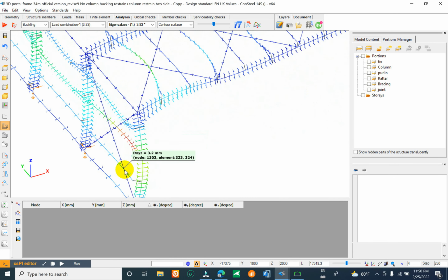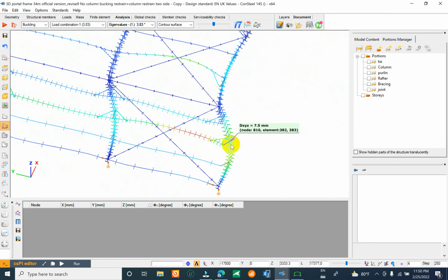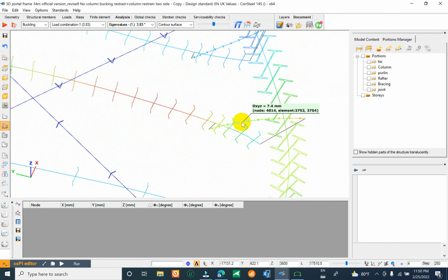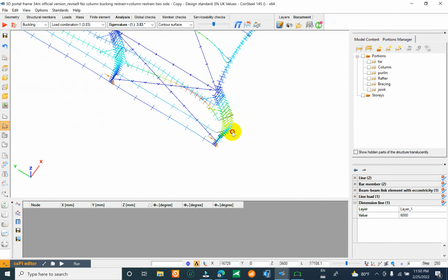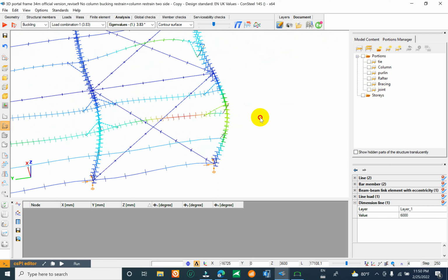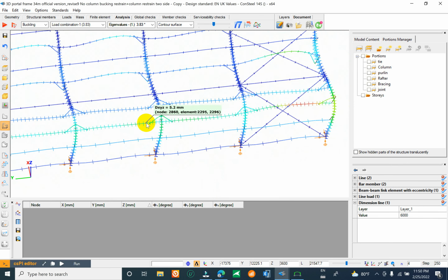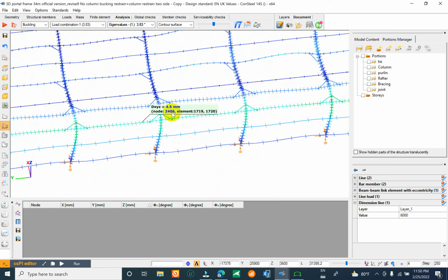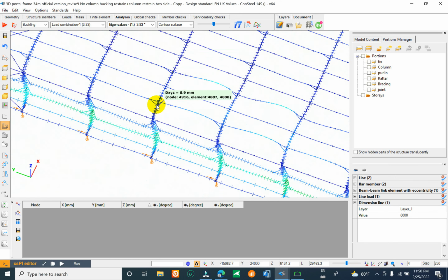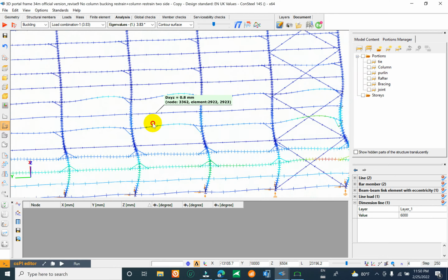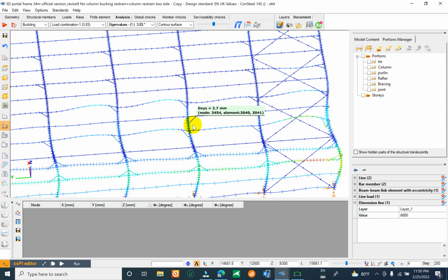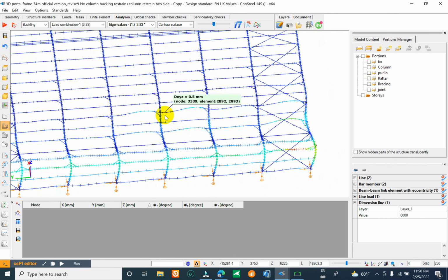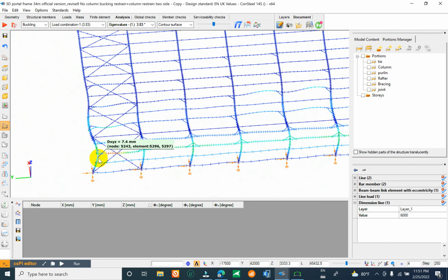So in this case we include the restraint. You see here about the restraint, our restraint and our purlin work together, you can check, to reduce out of plane deformation. You can see here the rafter now does not have much deformation out of plane. You also have some, but it's very little, about 2.7 millimeter or about 1.3 millimeter. You can check here in the column.